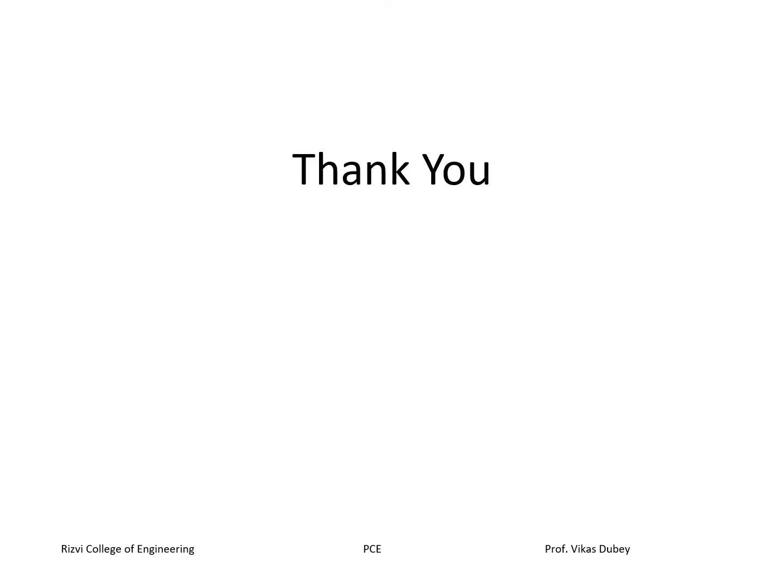In today's lecture we have seen the communication receiver and its different parts, then the SSB receiver, and then the ISB receiver. Basically, in all three receivers we have double conversion, because in a high band or congested frequency band, double conversion is very helpful: one mixer will generate the high frequency while the other mixer will generate the lower IF frequency. The advantage of the lower IF frequency is that it gives good selectivity and stability. We have also seen the differences in the block diagrams.